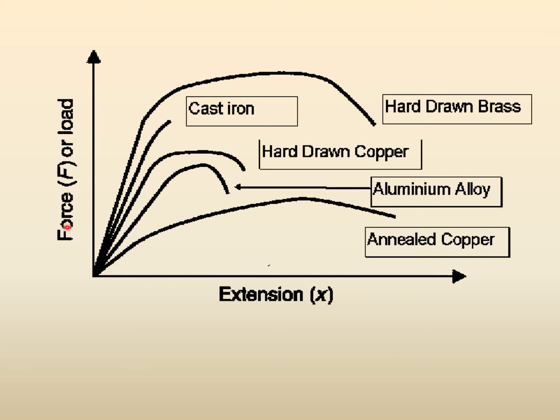But in terms of strength, this is low strength, this is higher strength, this is higher, this is even higher strength. Okay? So brittle can be of low strength, brittle can be of high strength. Similarly, ductile, you see all these ductile curves. The ductility of this is very high because it deforms until here.